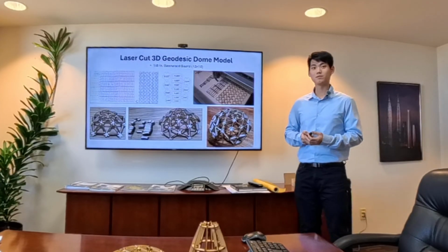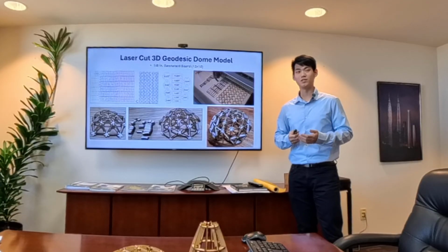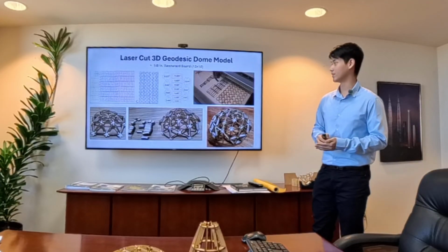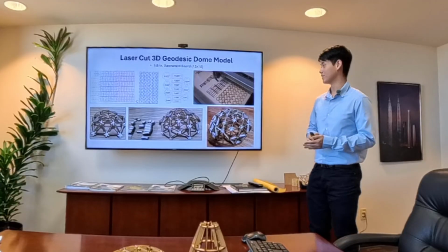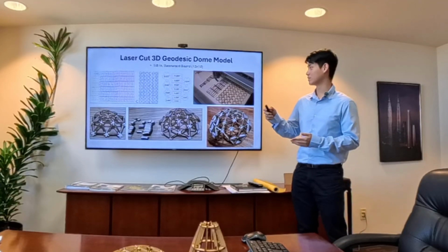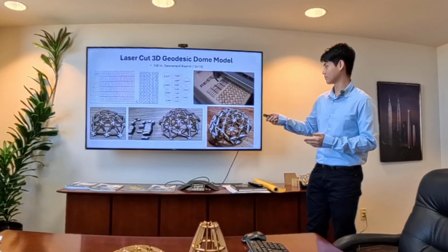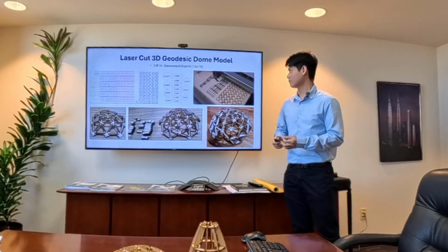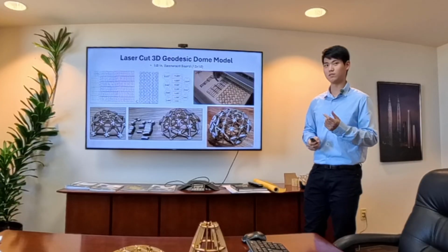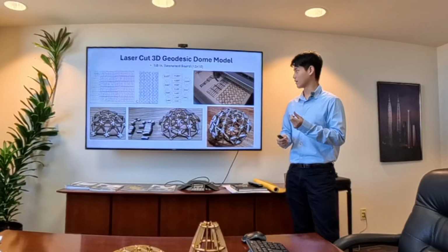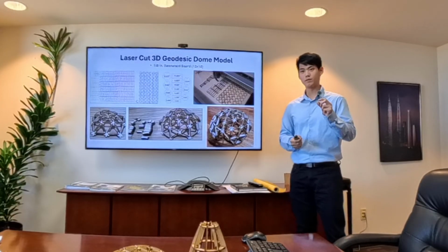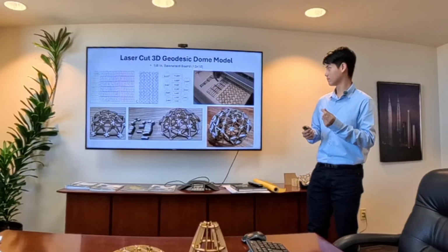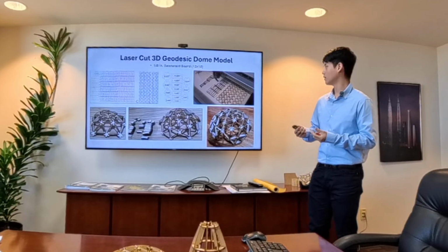A big part of this internship was going to the NJIT makerspace, and over there was a laser cutter. This was the first thing we made, a geodesic dome, which we made in the first week. The thing with laser cutting is you need to be very careful with the connections, because you need to consider the kerf of the laser when modeling your designs.